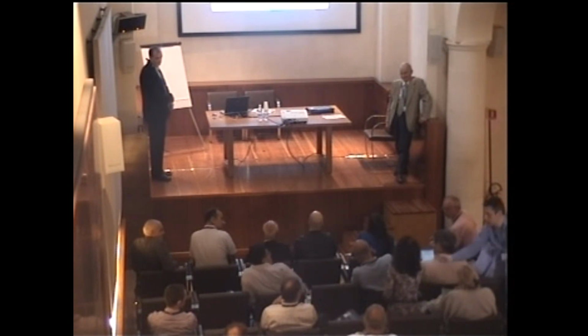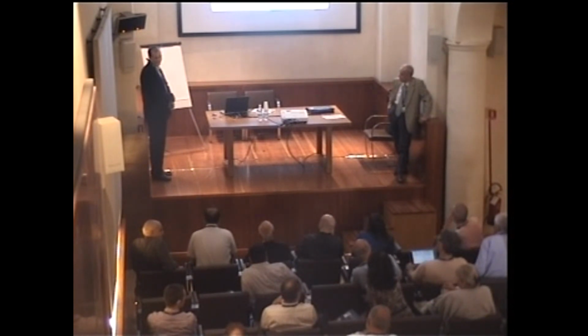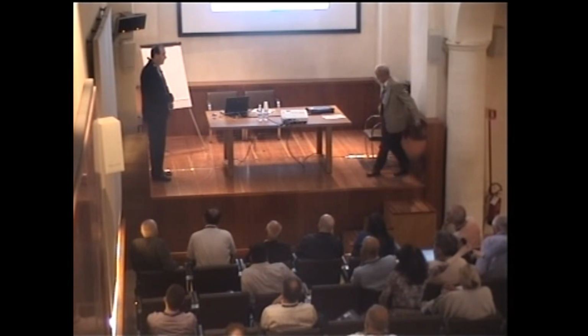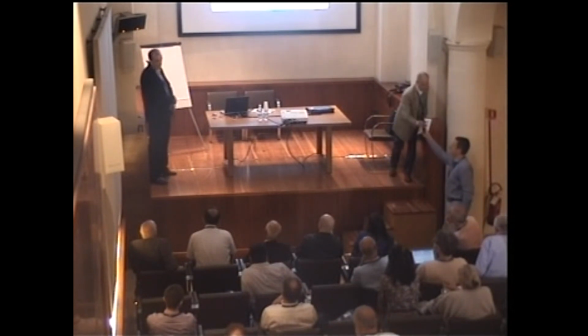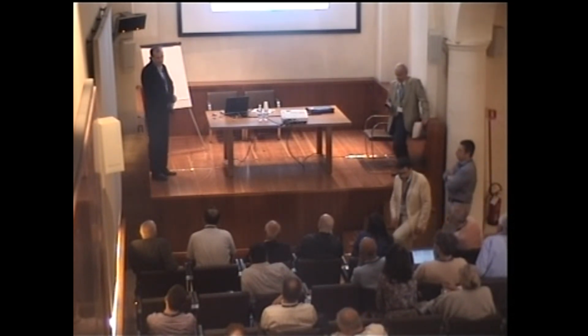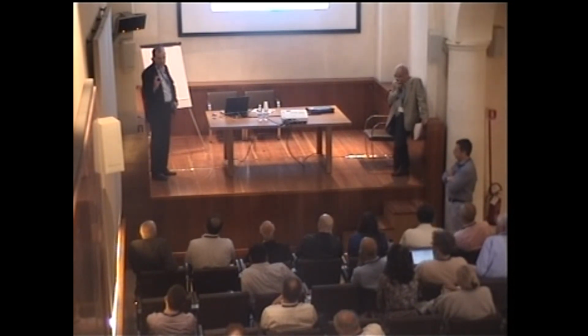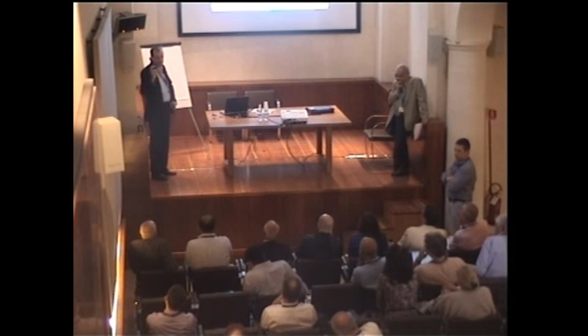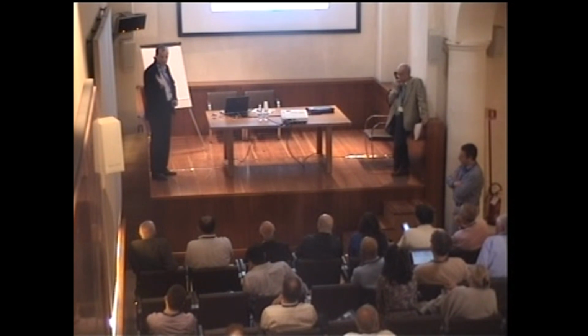I'm interested in control. Could you please comment what kind of control you apply, specifically what you control, what's your control algorithm, etc.? We can use very classical PID control, but we try to be more artificial, and we use a nonlinear controller developed by Professor Nayfeh, the saturation control, which is an additional nonlinear oscillator coupled with the basic structure by a quadratic term. And we can use some profits from this coupling. But for a rotating structure, we have to think whether it is an advantage or not.